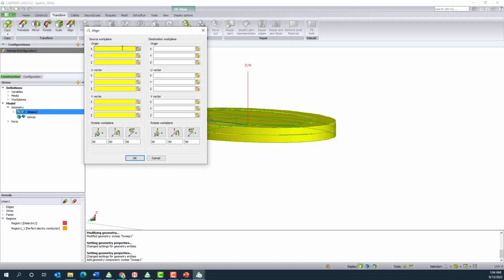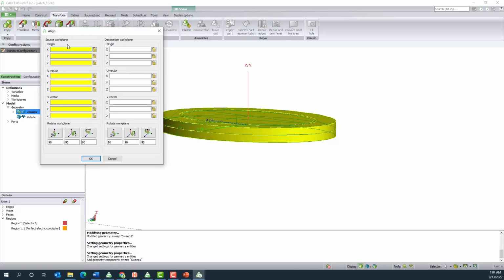Click that. I have these coordinates available, so I'm going to punch in those values. Probably you can work with your geometry appropriately. I have them handy, that's why I'm punching them in over here. Okay, 0 and -2.6909667212 and 1.27100800165 plus 0.003. These are the offsets I already gathered.